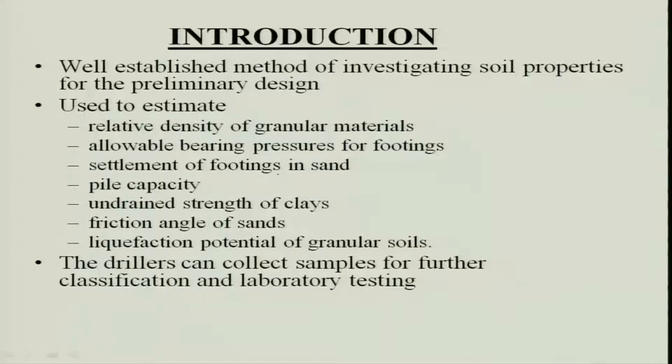So, last class I finished the plate load test. Now, the next field test is the standard penetration test. It is a well established method, particularly for investigating soil properties for the preliminary design. Generally, it is used to measure relative density of granular material, allowable bearing pressure by means of correlations, pile capacity, and friction angle of the sand.